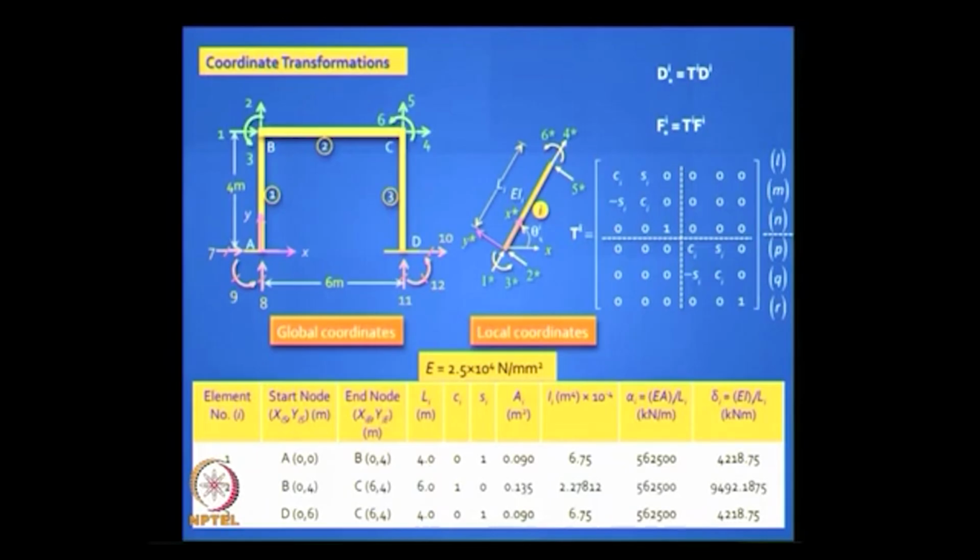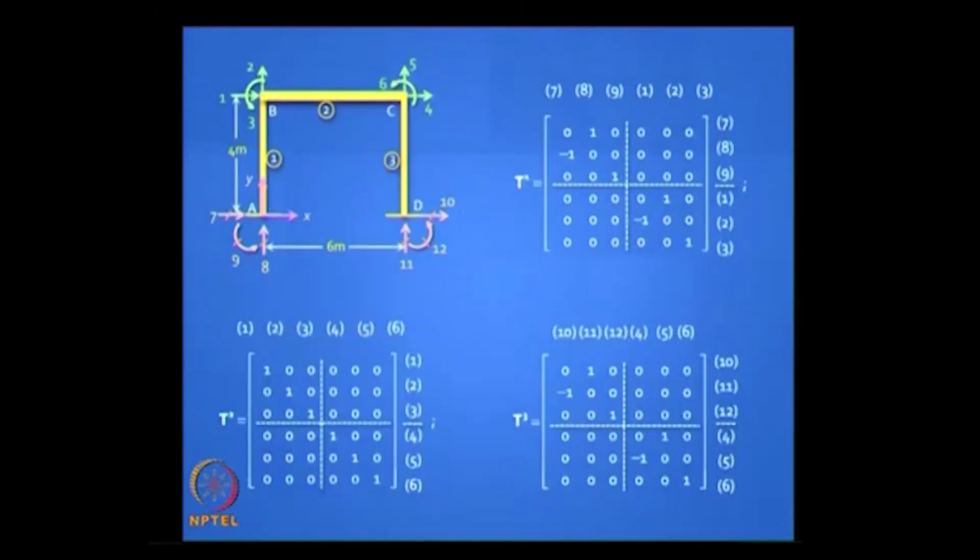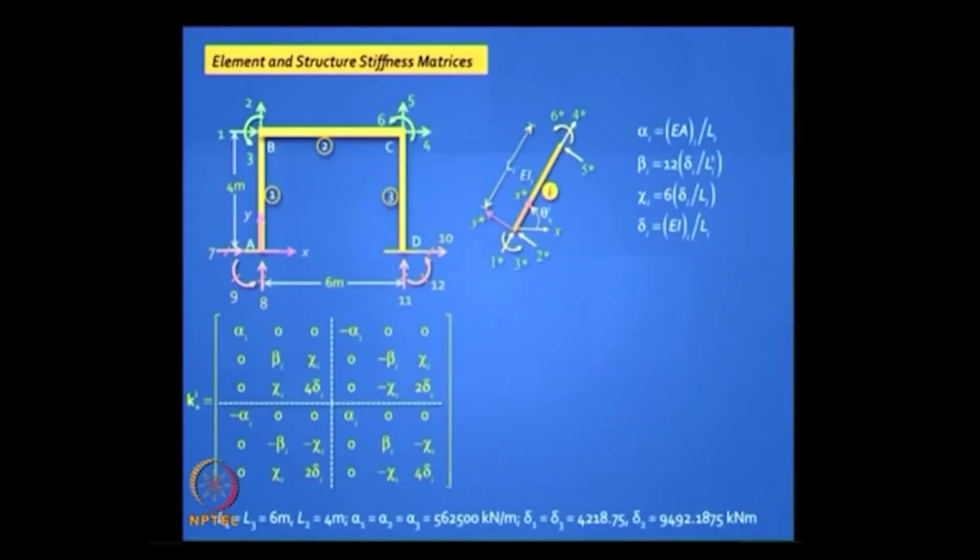So this is straight from that, you have 6 degrees of freedom which are active and 6 which are restrained. You can generate the matrix for all of them. We have done this before, 3 elements, but now when you write down the stiffness matrix you have to make a small correction for P. But do you know P? Yes, we know, there is a P for element 1 which is 2P, and for element 3 it is P.